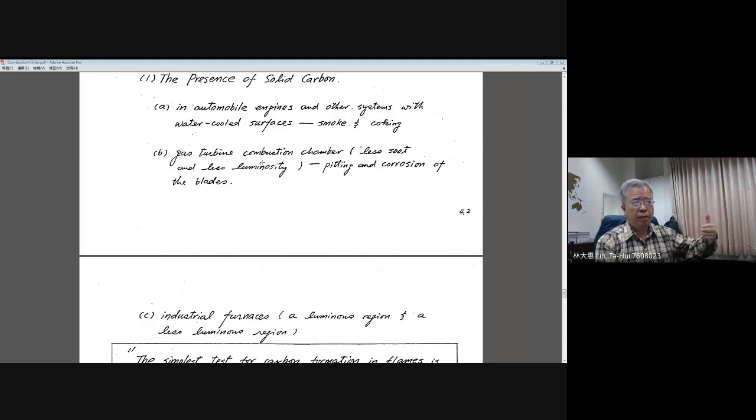go through the gas turbine combustor in two ways. Primary air goes in directly for the combustion, but there is a secondary air flowing and injecting near the surface of your combustion chamber for cooling. Okay, which means in this situation, we understand for the gas turbine combustor, we need a good atomizer, and the atomization is pretty good to produce efficient burning. Then the soot formation may not be very strong. They just have a small amount of carbon particles.